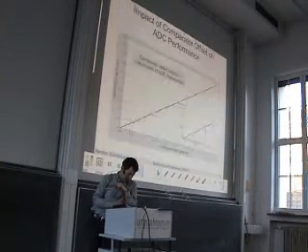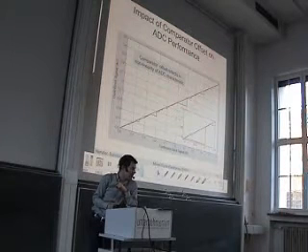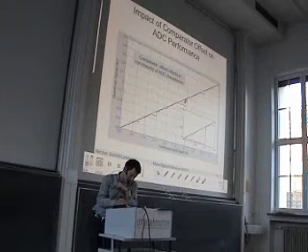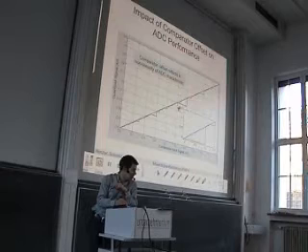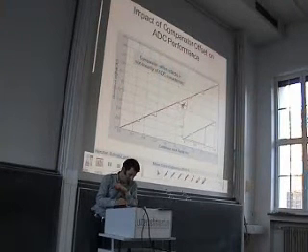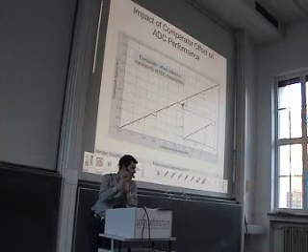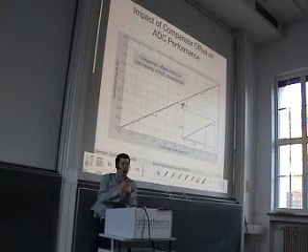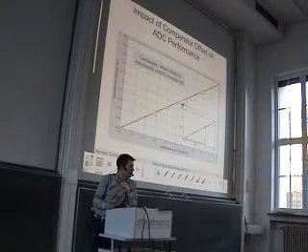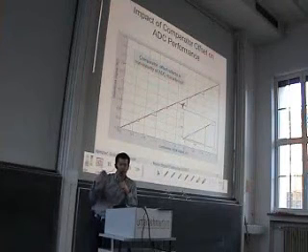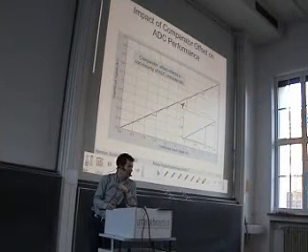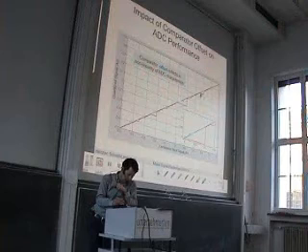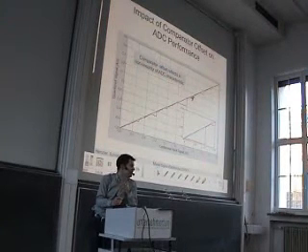And you can see here also that the error is different in magnitude. So here you can see there is a region where the error is huge. So this is the case when you enter this problem region already in the first cycle. Then you might have a voltage that does not fall into this region in the first cycle, but maybe in the second or third cycle. And depending on the number of cycles, when you fall in, your error is large or medium or smaller or even less. But it's there.